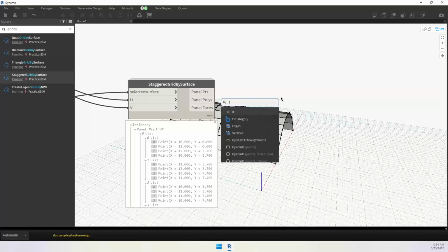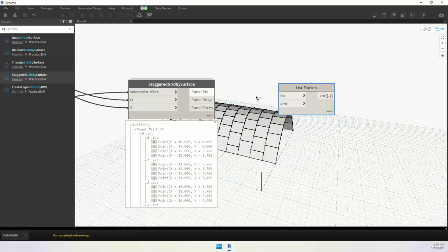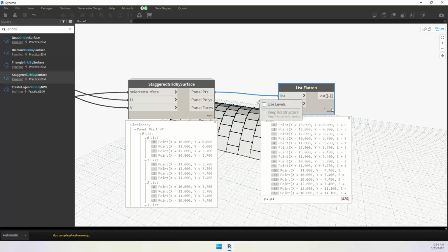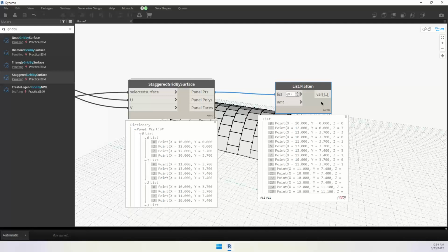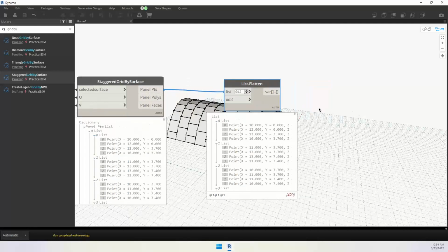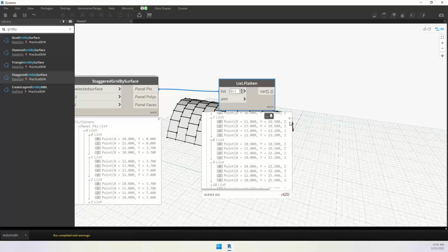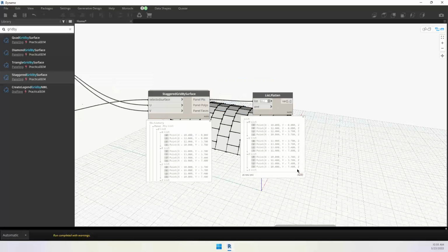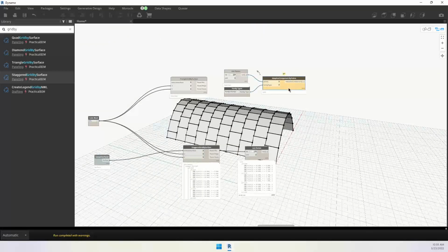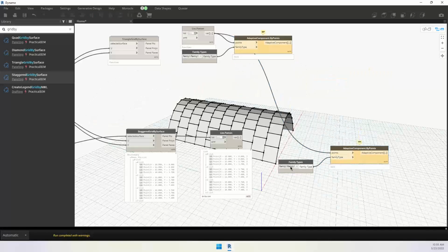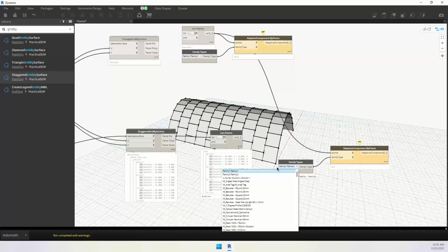So flatten, flatten. So this. So L1, L2, L3, till how many panels I have? 104 panels. Okay, well, how do I create this? The same process again. So adaptive component, this Control C, Control V. I'll duplicate this, and this family is going to be family 2,